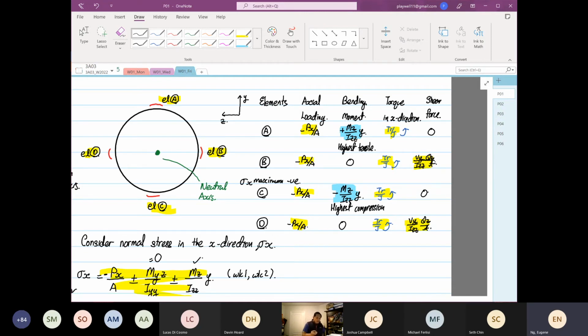Now if it's based on shearing stress, that might not be true, which I'll do later when we go into week 8 and week 9, on which one to choose. But for now, I'm going to show you an example at one location, which is point C. You realize that point C is the position where failure will initiate and occur. So there's no point calculating the stresses at point A, point B, and point D to select your material. We're going to zoom into point C.